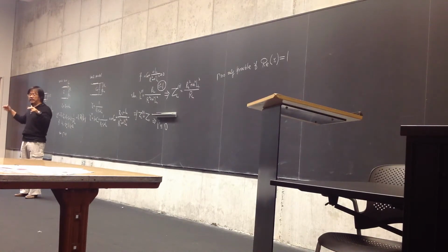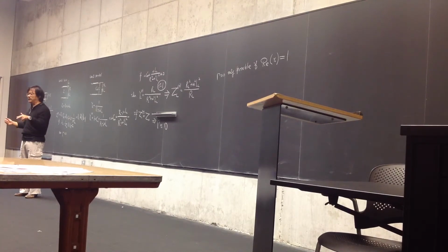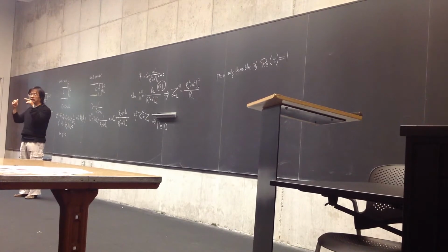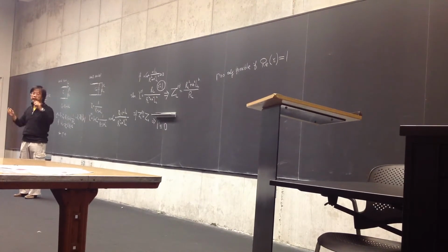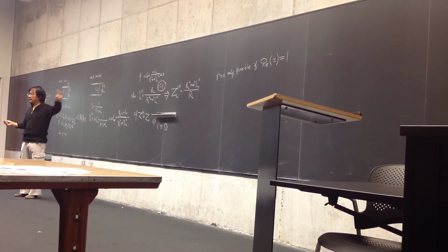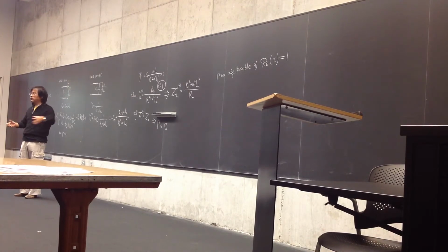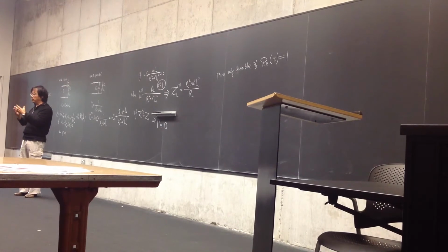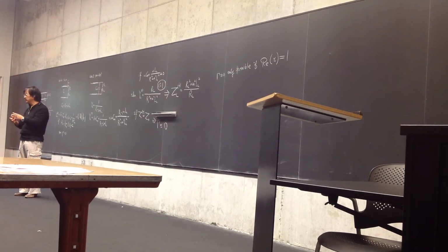And that real number, if you are doing the series connection, you are going to have no reflection only if the real part of your impedance, normalized impedance, equals 1. If you are doing a parallel connection, you can only achieve gamma equal to 0 only when the real part of the admittance equals 1. You know why?